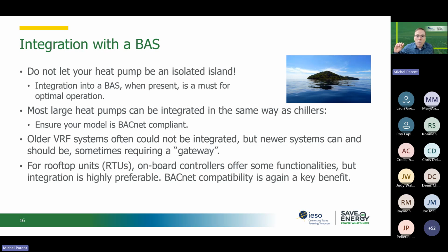So like I said before, you don't want your heat pump to work on its own. It will have multiple drawbacks if you do that. It will still give you savings. If you've got a rooftop unit that works on its own with its own controller, it's still going to provide you savings. But if it's integrated into your BAS, it will allow you to control the total building demand. It will allow you to control any supplemental heating in a more optimized fashion. So the benefits usually outweigh the cost of making sure it is connected to your BAS.